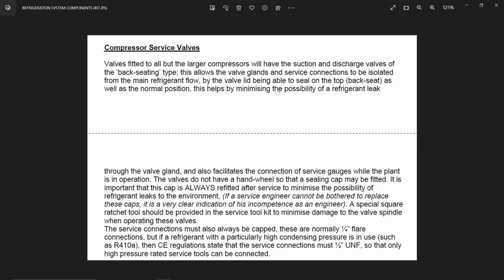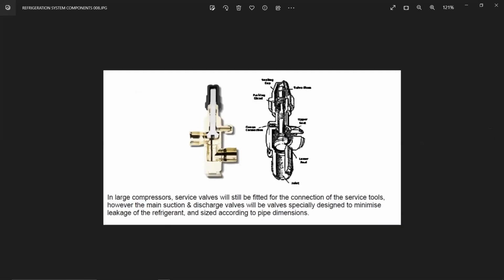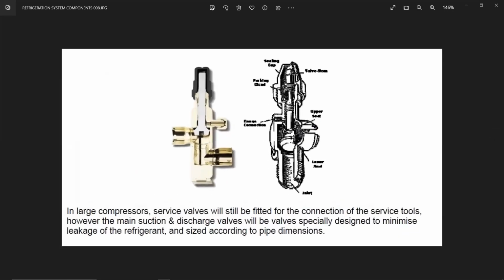Okay. So, sir, this is the reason why these valves are supposed to be either fully shut or fully open, right? Not in the middle position, क्योंकि बीच वाली position में it might just start leaking from the gland, right? Definitely, because it won't be locked on one side; like you see here, it is up and down. So in the middle you can't, okay, so it should be fully open or fully shut.